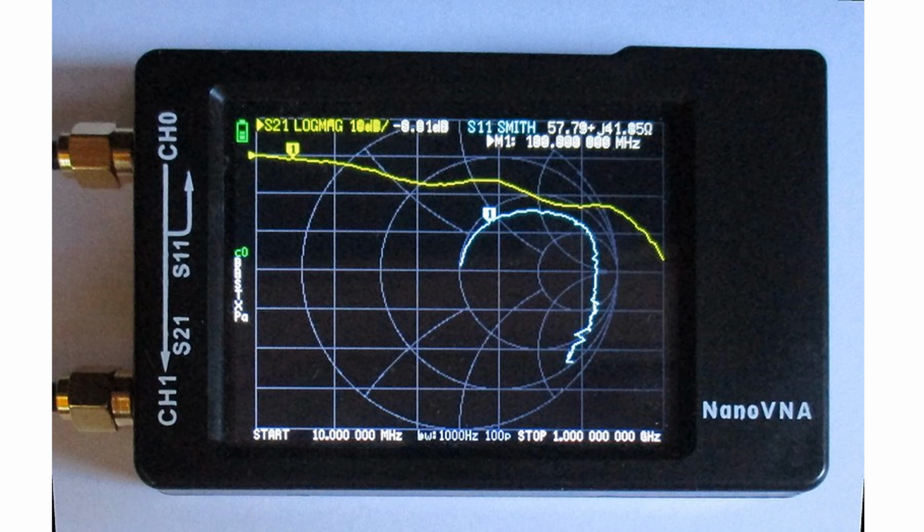Resonant frequency can also be determined using a nano VNA, which is a relatively cheap and affordable equipment for the amateur radio operator compared to conventional network analyzers, which are large and costly. Resonant frequency will depend mainly on the length of the driven element in relation to the wavelength. It will also depend on the speed of electromagnetic waves in the material used.